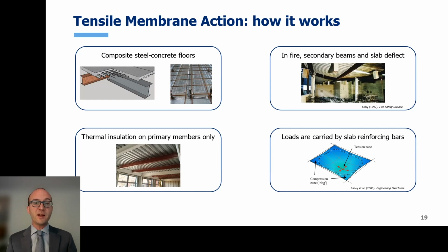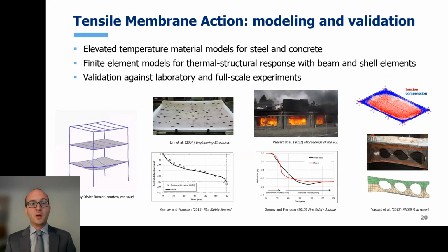The slab deflects as a membrane with a tensile zone at the center, and that's why it's called tensile membrane action. Since observing this behavior in the large-scale experiments in the UK, the behavior has been reproduced both in laboratory tests and in large-scale natural fire tests. The community has also validated numerical models to capture this behavior.